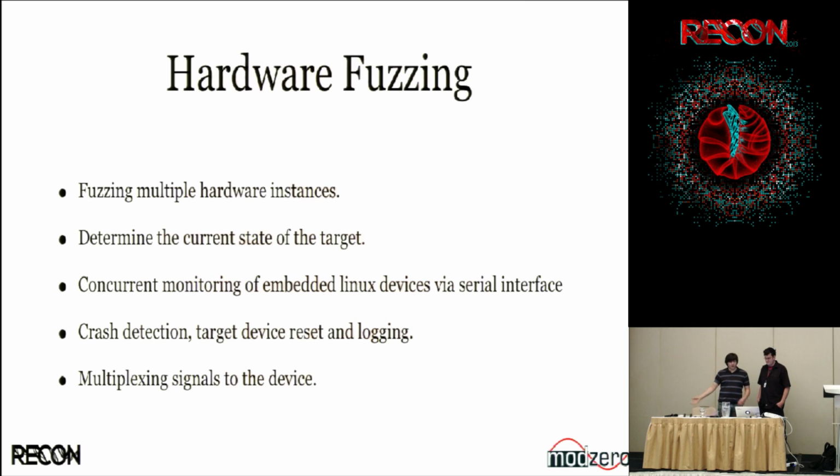Again, monitoring is another big thing. If you're monitoring and you see something's crashed, you can reset it with the hardware as well. I mean, that's why it's hardware. We can toggle a pin, pull it low, or we have maybe a pass transistor, cut the power from this board, turn it off, and start it back up. And the other important thing is we can do much better logging than if you were just to use an FTDI, for example, because in the FPGA you can implement much bigger buffers.